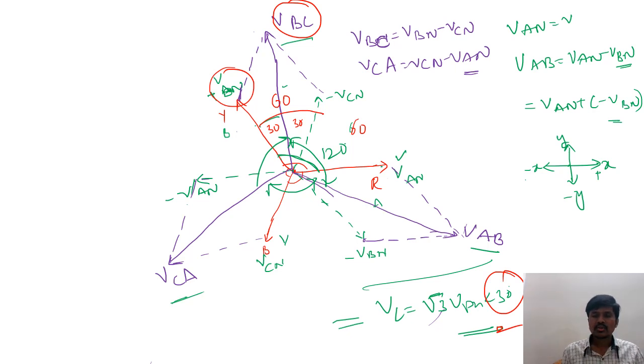So this is going to be seen in the case of star connected load as well as delta connected load. In delta connection, for currents we are going to get the line current equal to root 3 times the phase current, which also has a 30 degrees phase displacement. So in this way you can conclude the three-phase system for star connected load. Thank you.